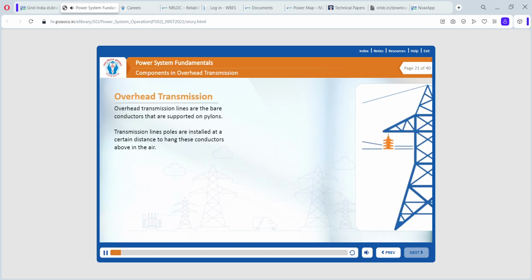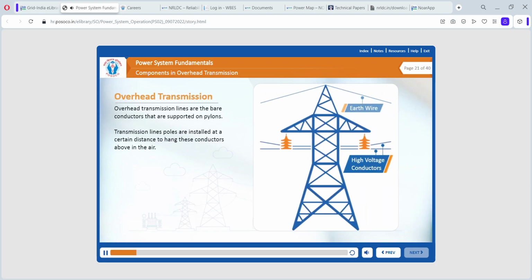An overhead line consists of conductors and ground wires, towers, insulation, hardware, and foundations. The transmission line conductors are specialized, with large cross-sections and relatively few strands. Normal AC power lines use phase conductors with a central core of a few steel wires, surrounded by a sheath of many more aluminum wires wound in helices of alternating direction. Click each part to learn the importance.